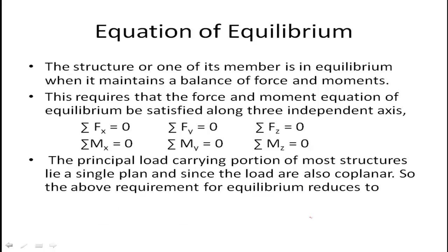should be equal to 0. But as we know, the principal load carrying portion of most structures lies in a single plane, and since the loads are also coplanar, the above moment requirement for equilibrium reduces to summation of forces in x direction equal to 0, summation of forces in y direction equal to 0, and summation of moments in z direction equal to 0, which you will understand with the help of an example.